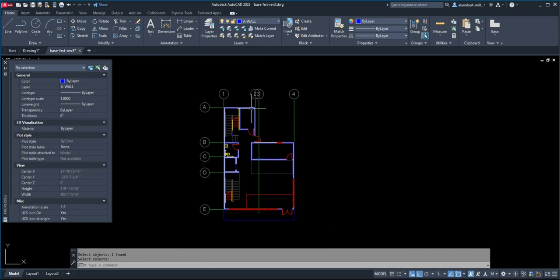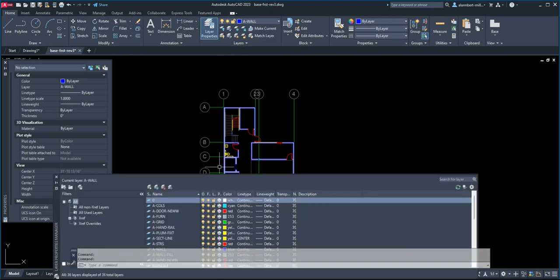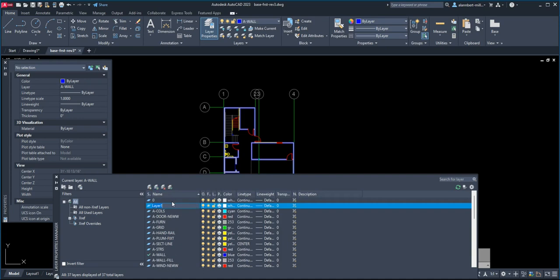So to start this one, we are going to create a layer again, and we're gonna name it a reflected ceiling plan, or RCP. So everything that's about reflected ceiling plan, I'm gonna put an RCP on it. It might not be conventional per American graphic standards, but I want to put ARCP for reflective ceiling plan, and I'm going to put their headers, HDRs, or I can put in HA headers.